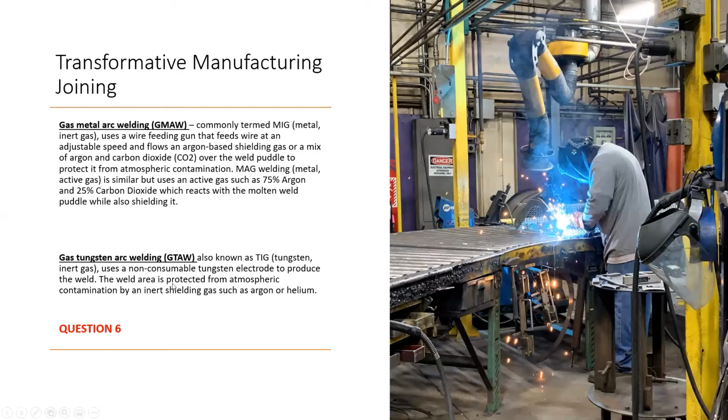This is a lot more complicated. It's a lot more challenging, and it requires additional certification to be a TIG welder versus a MIG welder. So you see a lot of MIG welding in the site furnishings world just because it's a little bit more common. It's a little bit easier to do. It's a little faster to do. So it's a little bit less expensive to use MIG welding versus TIG welding.